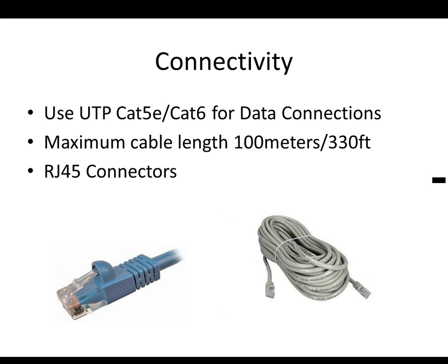To connect these cameras all together, you would use an unshielded twisted pair, Cat5e or Cat6 for data connectivity. The typical maximum cable length is 100 meters, which is 330 feet, and it is connected with RJ45 connectors.